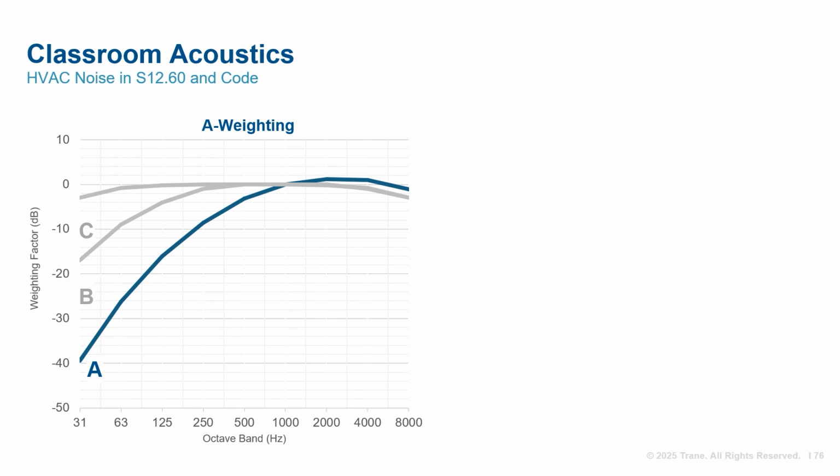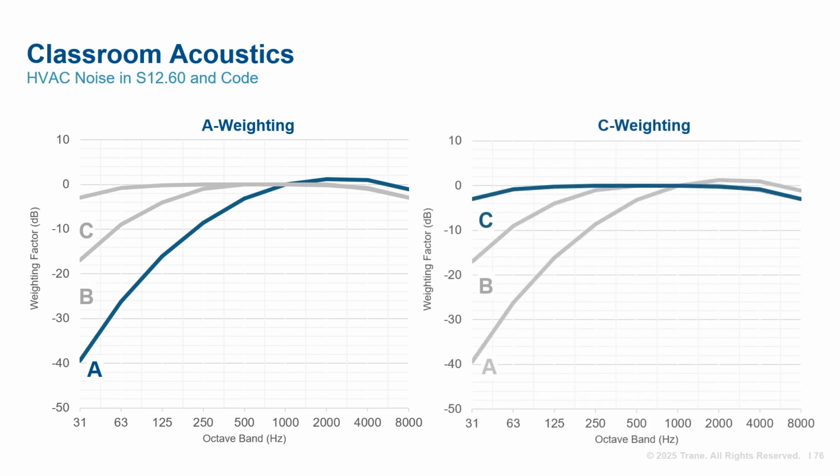over low frequencies. However, this can sometimes allow for noise sources with substantial low-frequency sound energy to adhere to the dBA requirement while creating an uncomfortable amount of rumble. The 55 dBC requirement ensures this does not slip through the cracks.